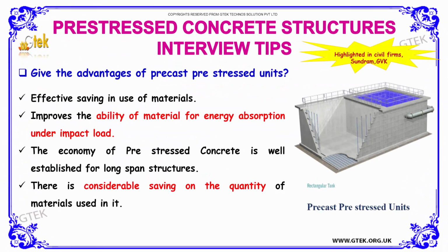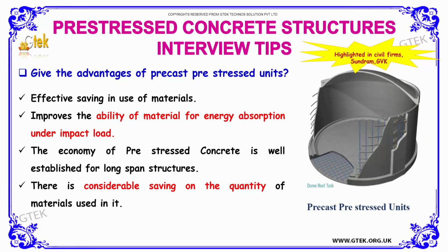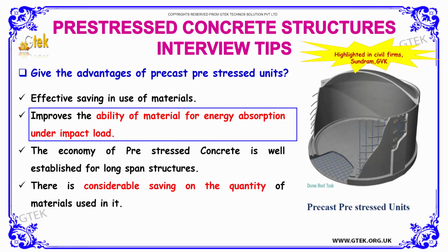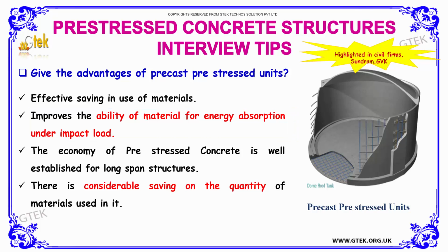We got the next question as follows. Give the advantages of precast prestressed units. The first and foremost advantage is effective saving in the use of materials. The second one is that it improves the ability of the material for energy absorption under impact load.